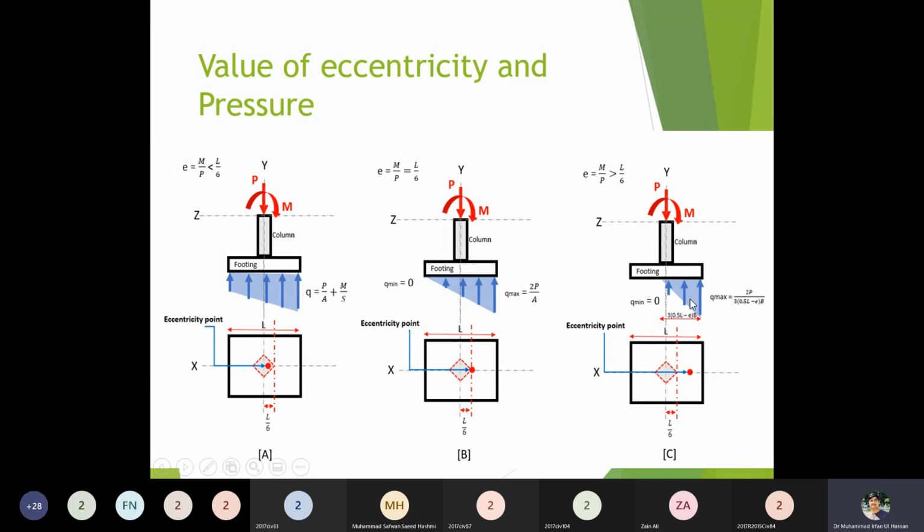So you can see that the effective part of the soil keeps reducing, so the best option is that I go with option A. I should select the size of the footing in such a manner that the total soil under the foundation can be utilized, so that all our soil is utilized. Excuse me, sir. It will be the left-hand side case.